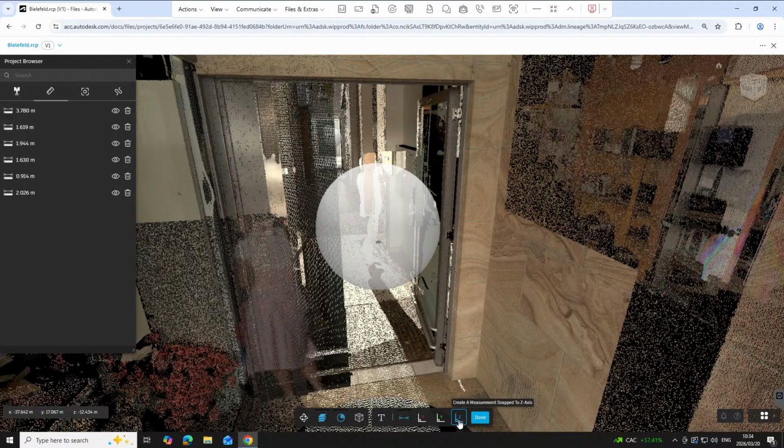You can limit this to the Z axis. Now if I move my mouse around, it actually limits me to the Z axis, which is quite nice. Now I get it as close to the... All right, so I can see that opening is 2.325 millimeters.